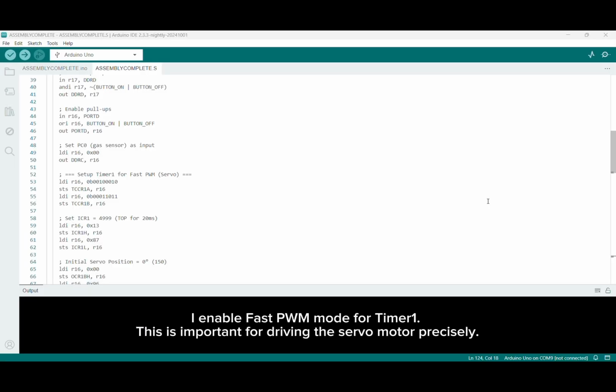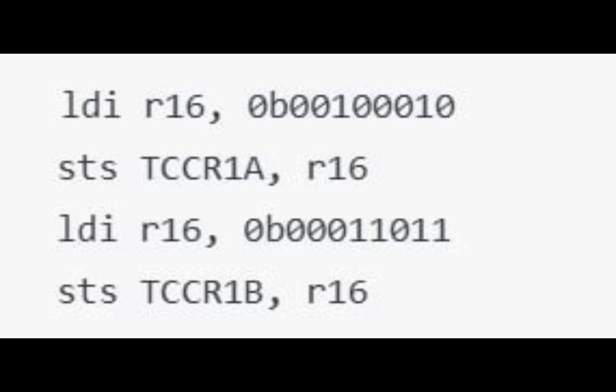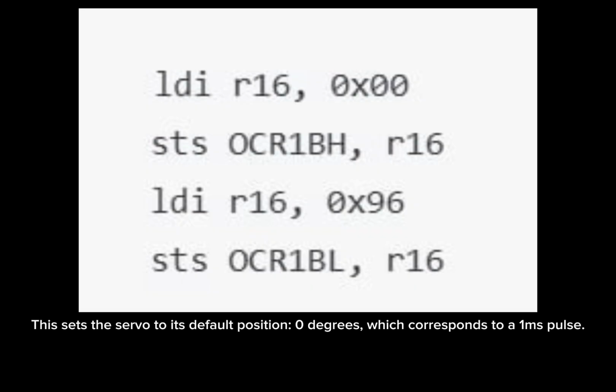Section 4, Timer1 setup for servo PWM. I enable Fast PWM mode for Timer 1. This is important for driving the servo motor precisely. I set the top value for the PWM to 4999, giving us a 20 millisecond pulse period, standard for hobby servos. This sets the servo to its default position, 0 degrees, which corresponds to a 1 millisecond pulse.